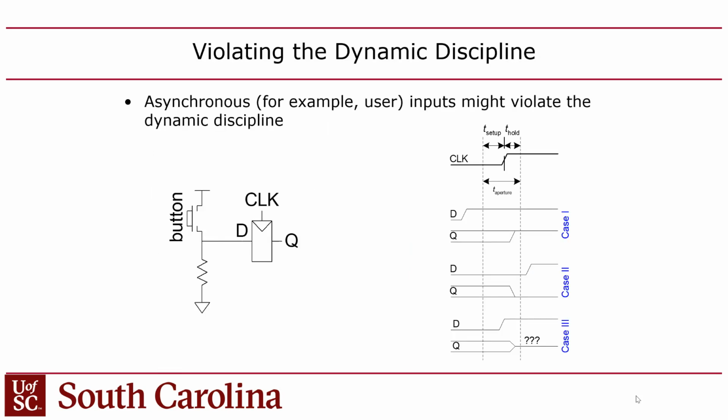Okay, so, all right. So basically, when you synthesize your designs, the CAD tool is going to tell you whether you've violated the setup or hold time. Now, you might say, wait a second, I haven't seen any violations in our design yet. Well, that's because we set the clock constraint. We told the CAD tool Quartus that the clock is going to run at 50 megahertz, which is a 20 nanosecond clock.